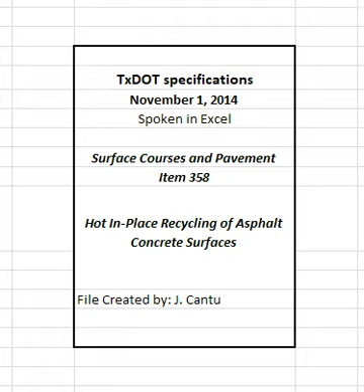4.9 Irregularities. Identify and correct irregularities, including but not limited to segregation, rutting, raveling, flushing, fat spots, mat slippage, irregular color, irregular texture, roller marks, tears, gouges, streaks, uncoated aggregate particles, or broken aggregate particles. The engineer may also identify irregularities, and in such cases, the engineer will promptly notify the contractor.